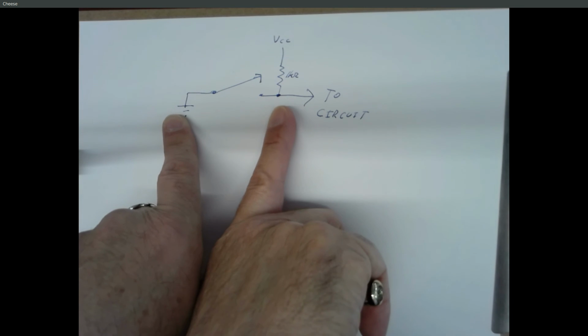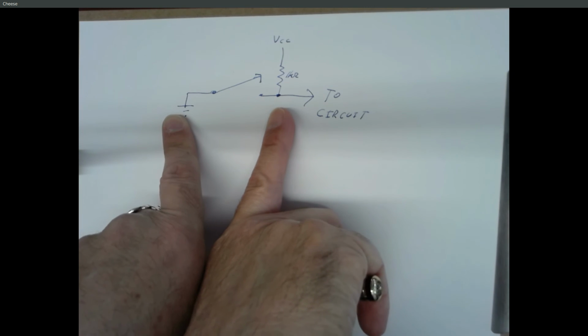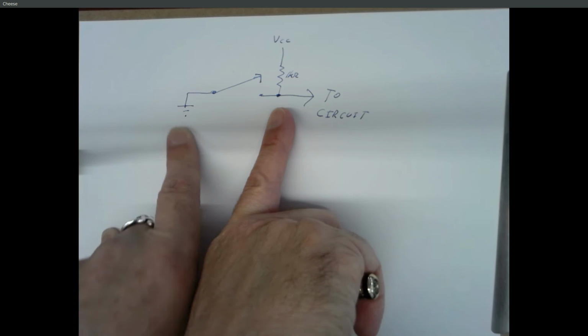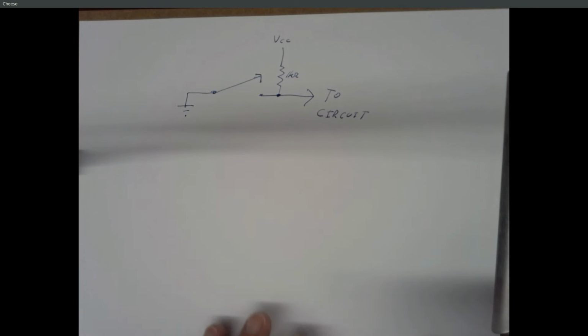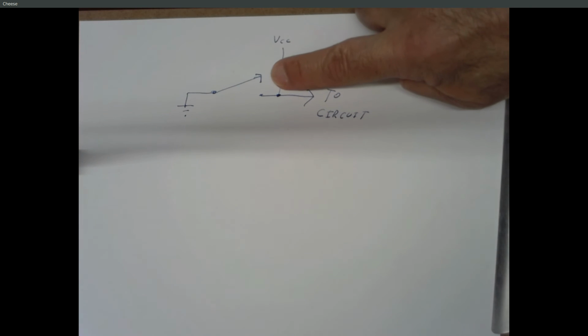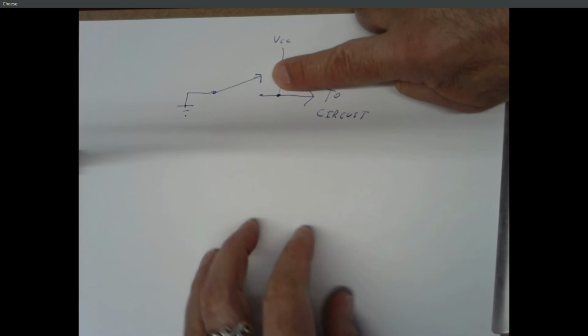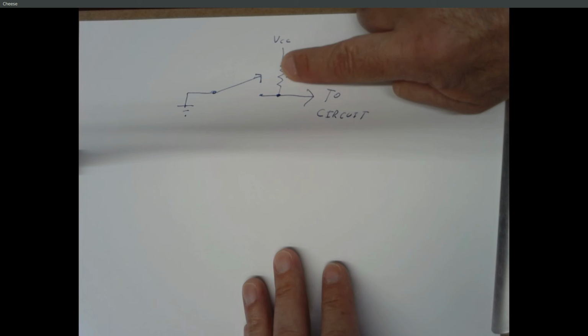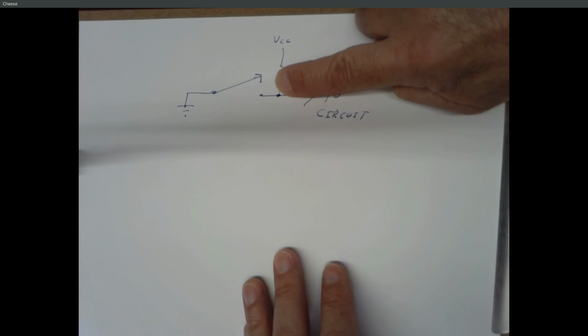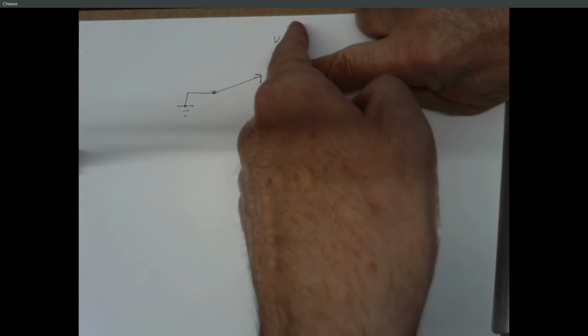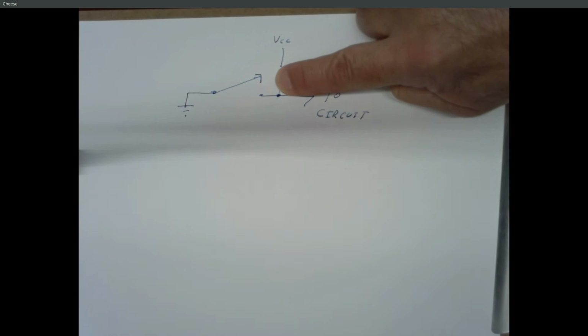And there are a lot of ways to try to do this that are not right. All right. So for example, if you leave off this resistor, because it's just a resistor, who cares, right? If you leave off this resistor, what happens when you close the switch? If you just put a wire here instead. You've got a short. You've got a direct path from power to ground. That's when your power supply makes that little clicking noise and the red light comes on.